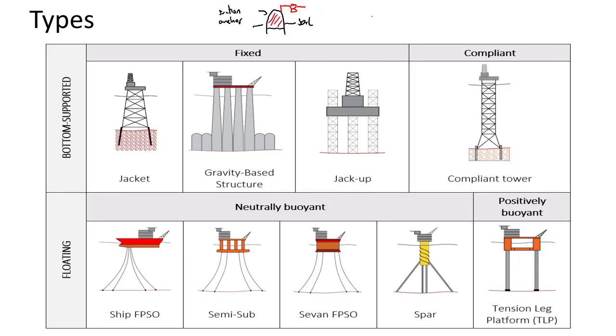The jack-up in regular configuration has the legs up when it's being transported, when it's moving from place to place. But then at some point, when it's exactly over the place where you're going to drill, for example, these legs are lowered using gears, using a hydraulic system with gears.